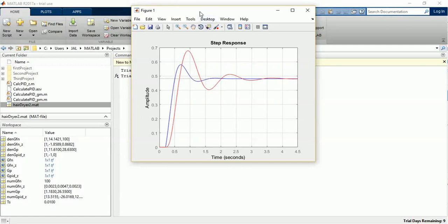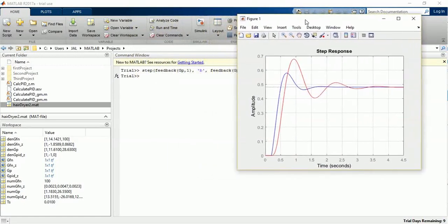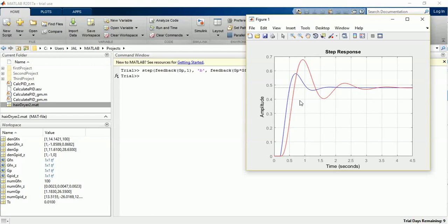So in order to see what happened, let's go back to the bode plot of the system with the filter and compare with the original one to see the correlation between the open loop frequency response and closed loop time response. In order to find again the bode plot, we are going to use the bode function of Matlab.